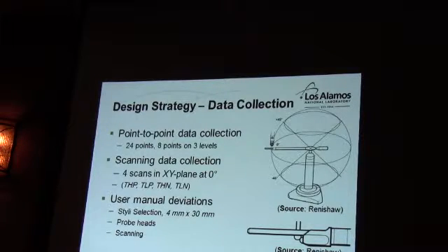So now we're worried about, is our direction vector there? Are we getting a lot of errors from our direction vector? Is it matching up? Is our radius going to be the same? Another issue is that now we're worried about this kinematic C here. If this kinematic C isn't above the center line here, then it won't trigger a point. So we may have lots of data, and then if the machine's moving too fast, we won't get any measurements from, as I mentioned, the probing vectors, from anything that's dynamic in the errors.